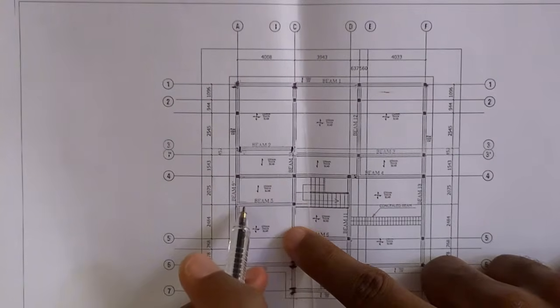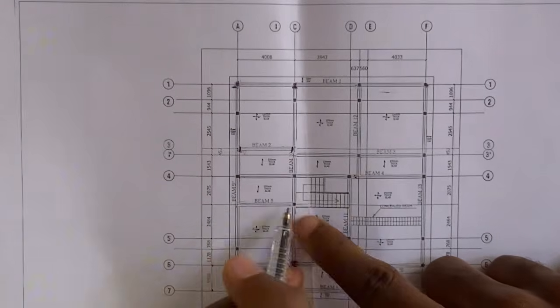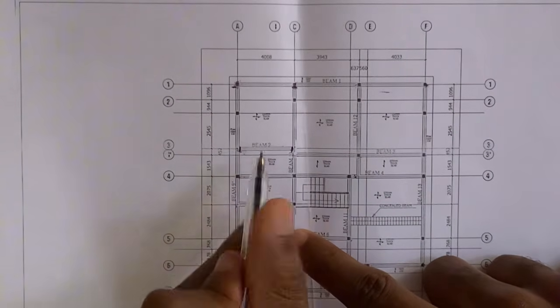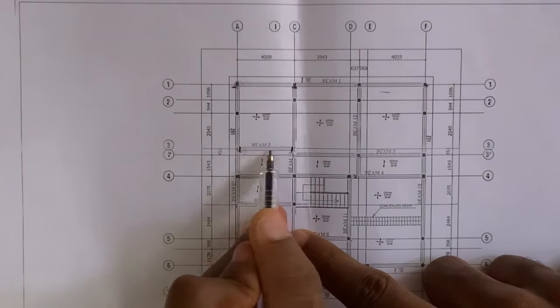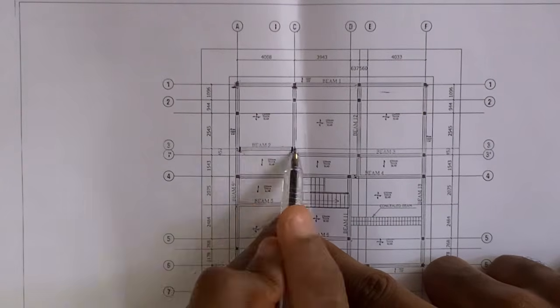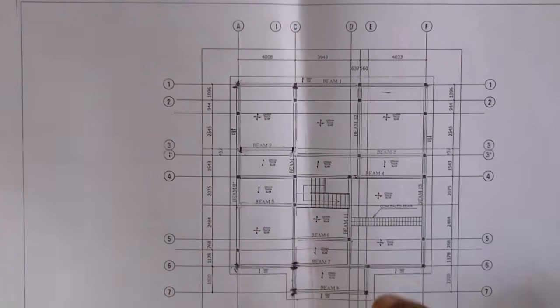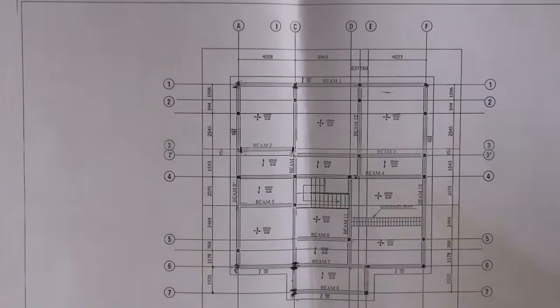So now it means that we're going to be minusing half of the thickness of this beam from both sides, which is the same thing we did in beam 2, meaning that what we had as the perimeter of this in-to-in dimension for beam 2 will be the same perimeter for beam 5. So instead of remeasuring, you just go and pick what you measured for beam 2 and bring it out to beam 5.